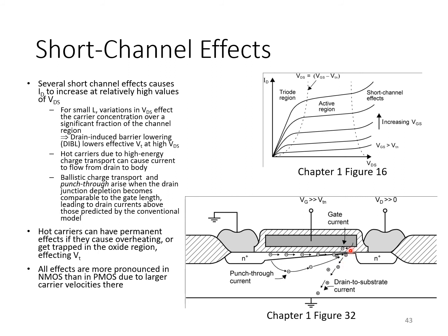Specifically, the regions right at each extremity of the channel region are implanted so that they're more lightly doped than the rest of the drain and source region. And so this so-called lightly doped drain region, of course applied on both sides of the channel, LDD, tries to mitigate the possibility of drain-induced barrier lowering in these advanced technologies.